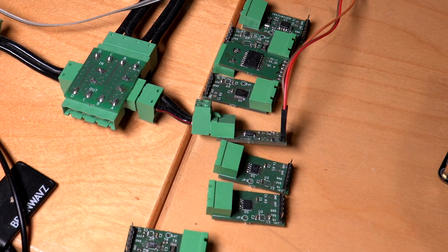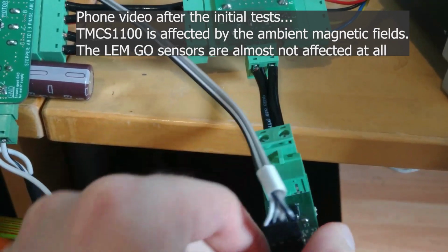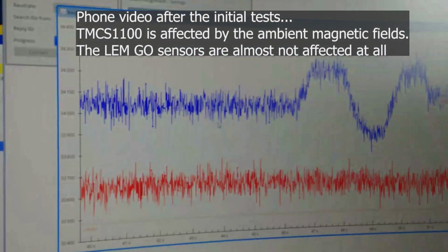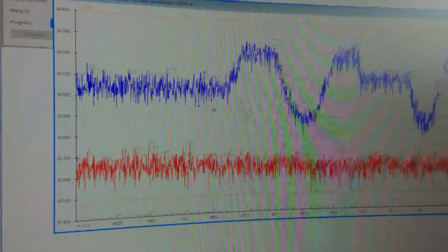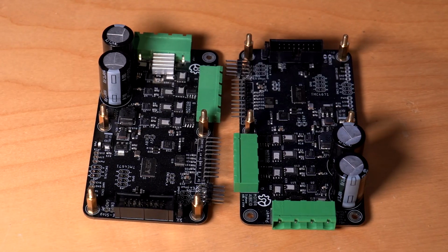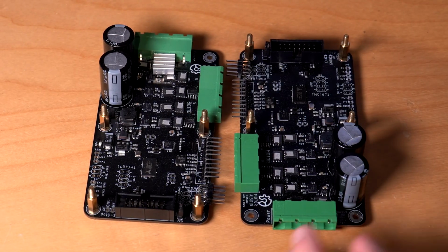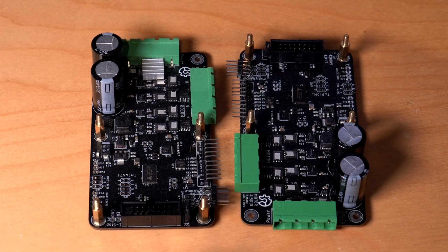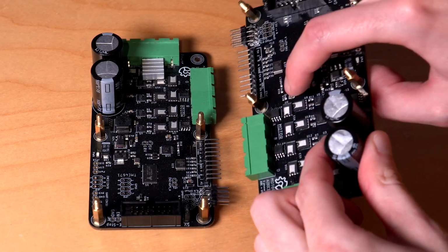The TMCS does suffer from external noise and offsets from external magnetic fields a bit more, and even the orientation matters for this sensor, but otherwise it was also a solid candidate. So I have designed an updated version of the V1.2 board and replaced the shunts, amplifiers and filters with these Hall sensors. These are what you can see here.